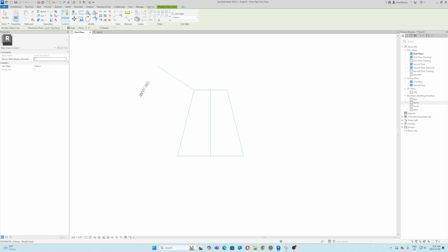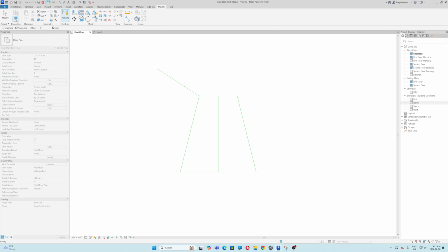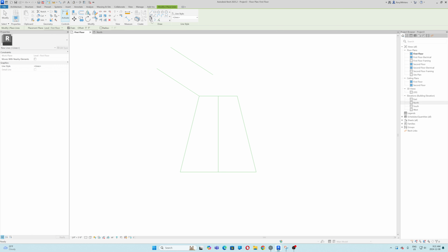And then I want to offset it 4 feet. It gives you the offset right here. And I want it on this top side. Again, type LI to get back to your tools. I want the top of the stairs to have a little bit of curve, and I want the bottom of the stairs to have a bit of curve too. Just a little bit, maybe 30 degrees.